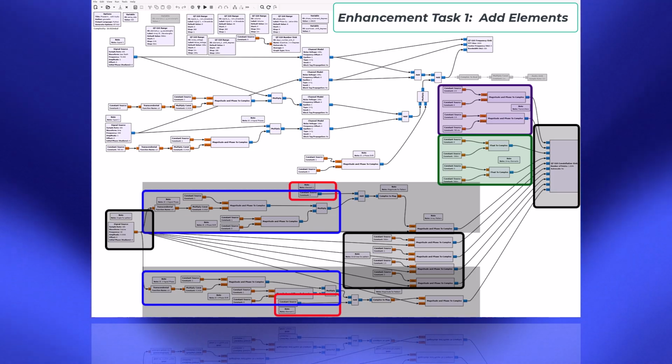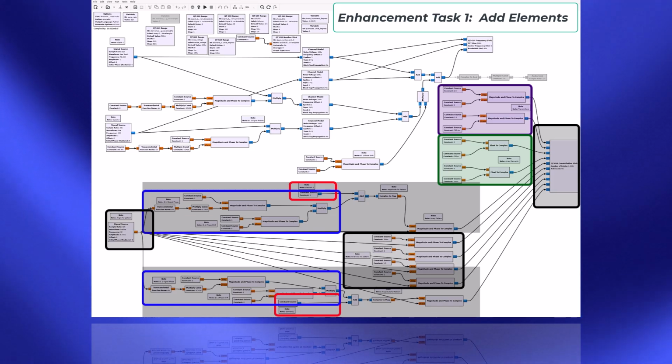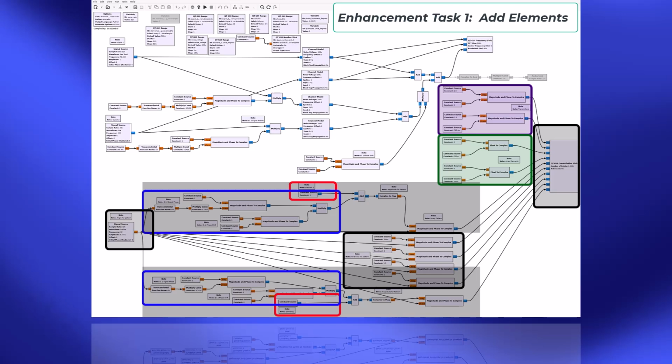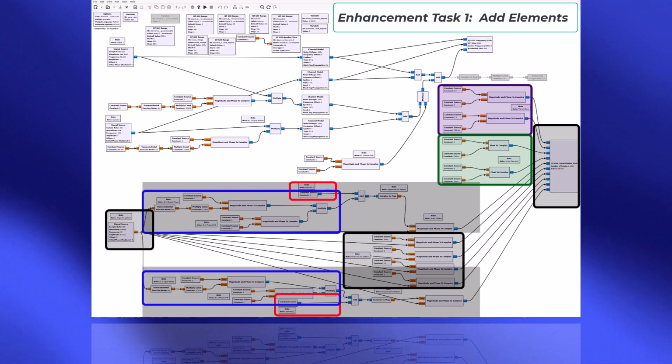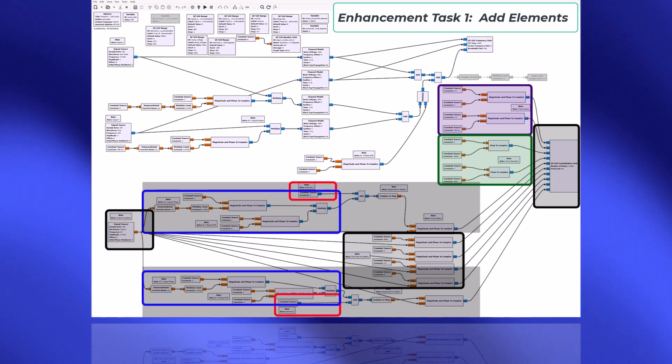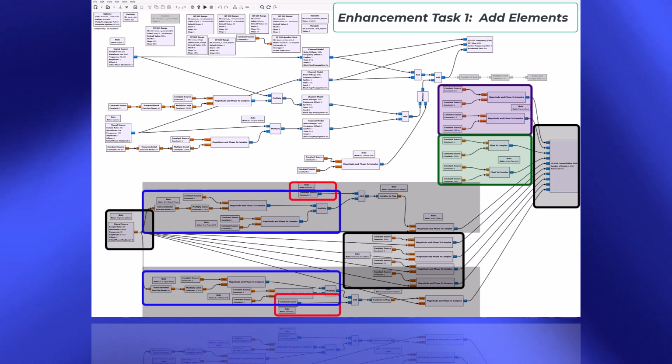And in a newer version, I've actually replaced the cosine signal with a sawtooth wave and set the constant multiplier so that that sawtooth wave in a linear manner varies over the full range of angles to serve as a reference and to do that in a little more linear manner. Also, you may consider changing the sample rate for the signal source block here.